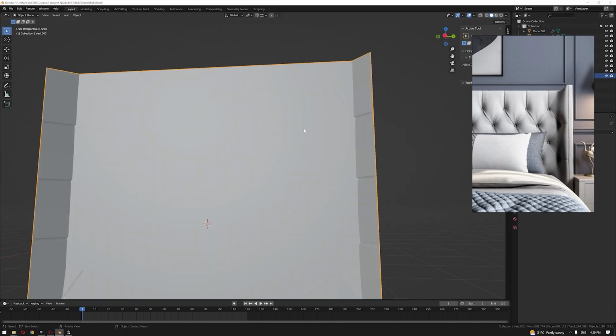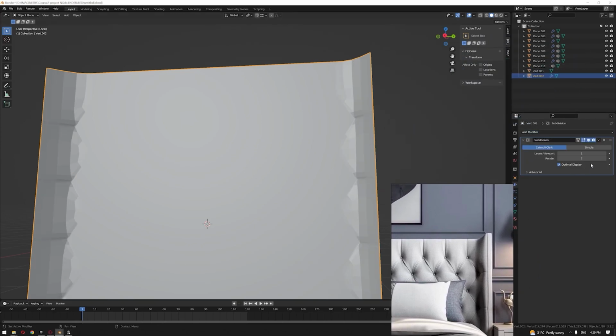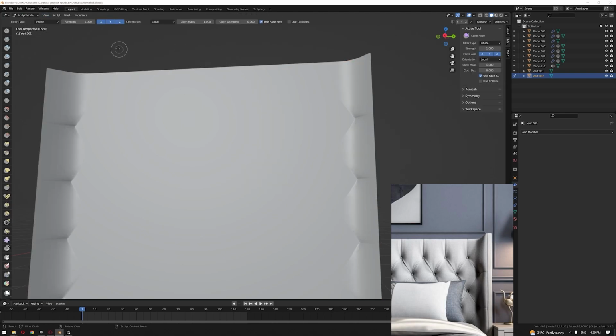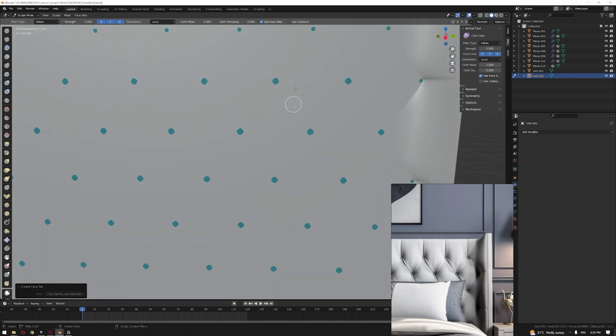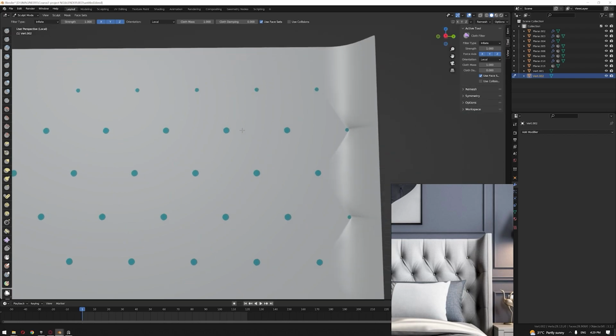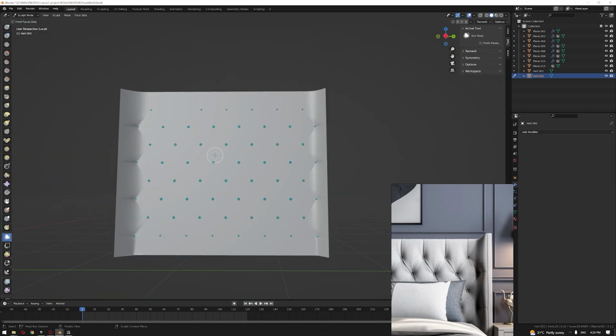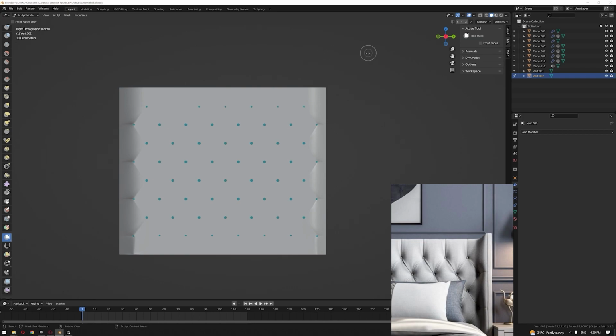And then let's get out of the edit mode and then add a subdivision modifier, apply it, add a shade smooth, go into the sculpt mode, and then go to the face, set face from edit mode selection, and then it will choose recently active selection. Go to one of them, hit Control W, just to increase the selection a little bit. And then we'll go to the mask, box mask, then select the outer edge as we don't want them to be affected.